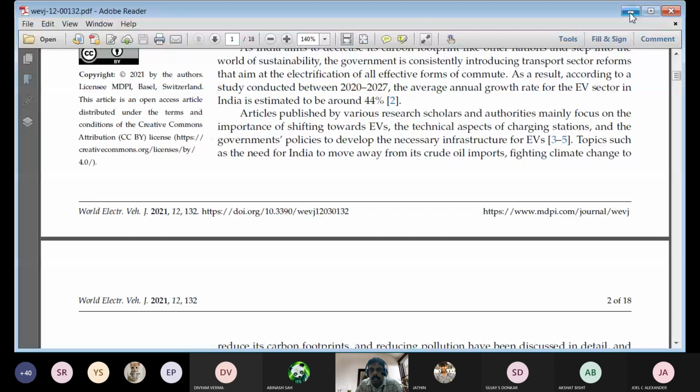Then, only a small fraction of the sun's solar radiation gets to Earth. That too, on the surface it varies due to various mechanisms on the way, that means diffraction, reflection, interference, absorption, etc. in the atmosphere. So we can expect almost constant radiation in a day beyond the atmosphere region, that is called extraterrestrial radiation. That is 1.36 kilowatt per meter square. That also varies according to the day, so some correction equation is there. It is given in the data book.